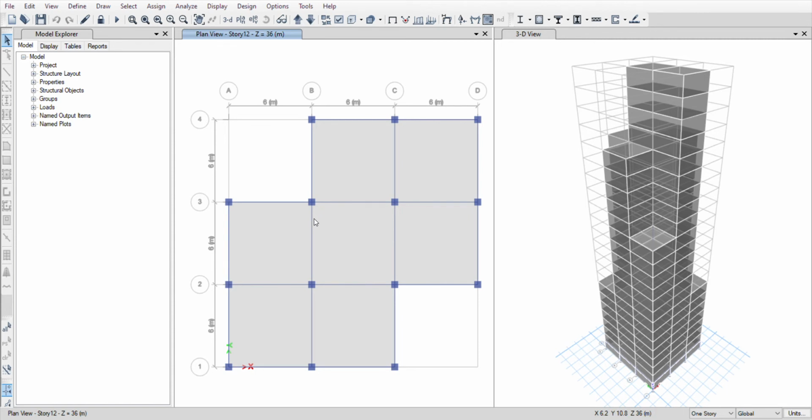The method of seismic resistant analysis for a building changes, but the entire procedure is the same. First we define, then assign, analyze, and finally design, and we review the graphs. Here I have already analyzed it, as you can see from the lock screen. That means I have already run the analysis for the different load cases, except dead and live, for seismic and time history.